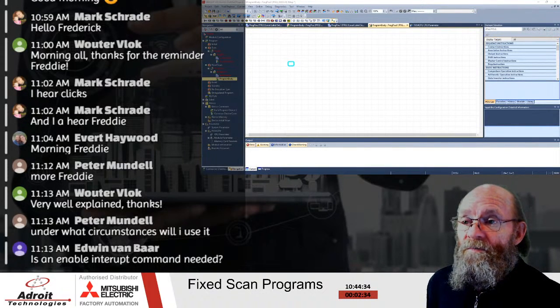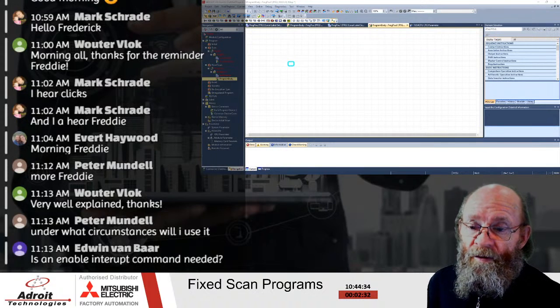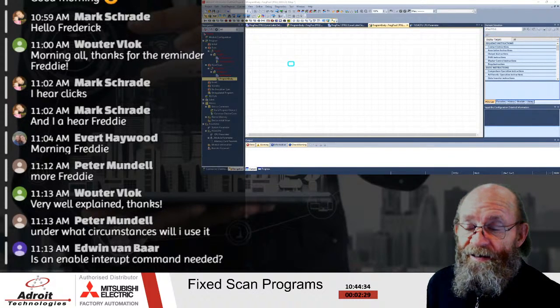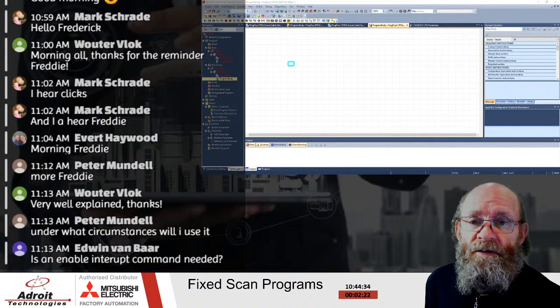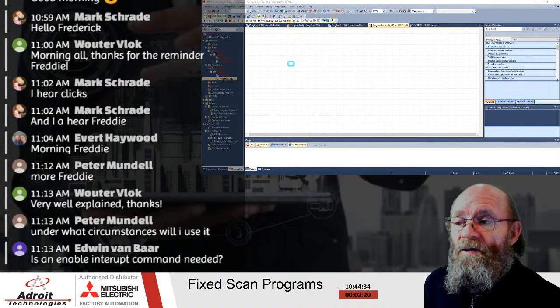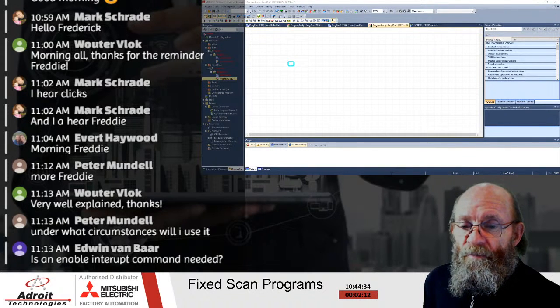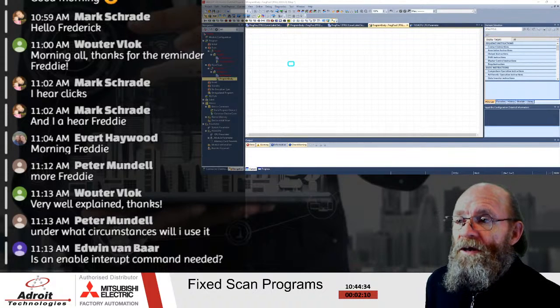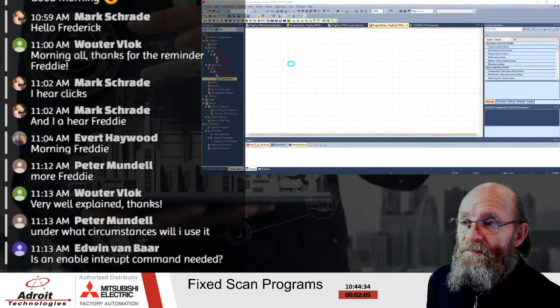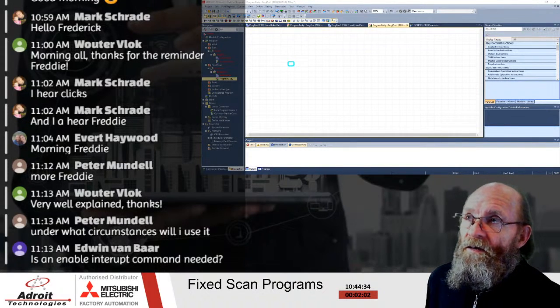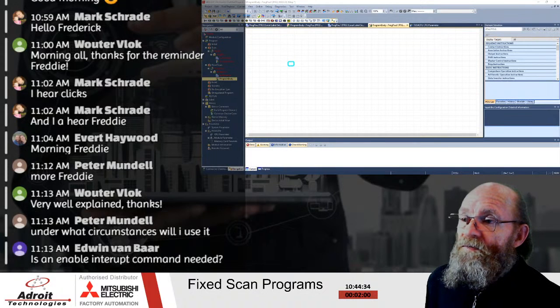So then you would maybe run a separate program to deal with dedicated scan times, where one would look at something specifically around timing, clock related information, where you can do a specific time recording, or you need to respond to something at exactly the correct time. Where else would one make use of an interrupt program?